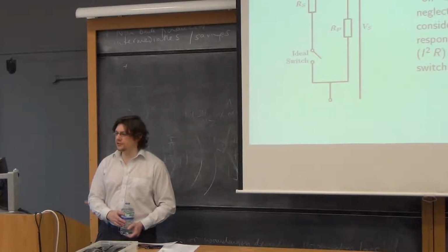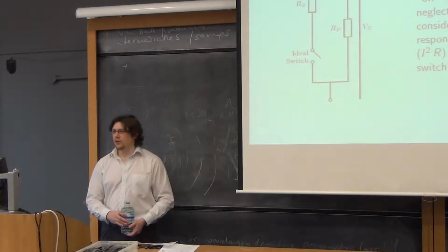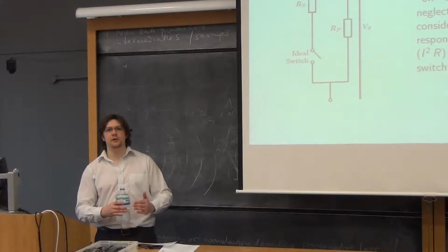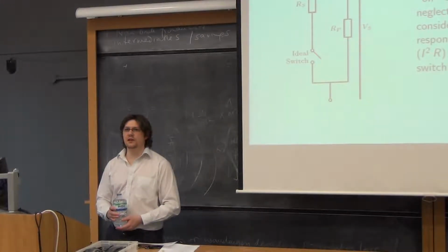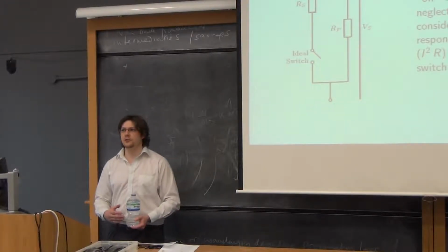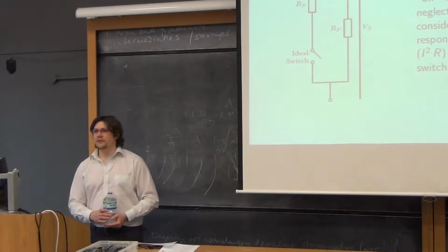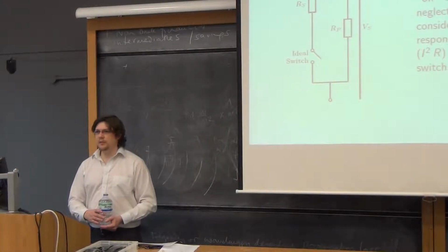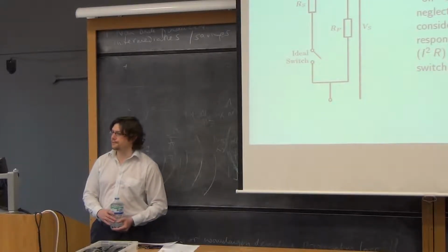Then we have a parallel resistance, and this is the resistance that dissipates power even when the switch is switched off. So in a real mechanical switch, there is almost no current flow between the two electrodes because there's a really big air gap, and air has an enormous resistance unless it's broken down. To break down air, you need about 1,000 volts for every millimetre at sea level at a reasonable humidity. So for 5 or 10 volt circuits, it's very difficult to make an arc. So RP is practically infinite, RS practically zero, and that's the situation for the ideal switch.